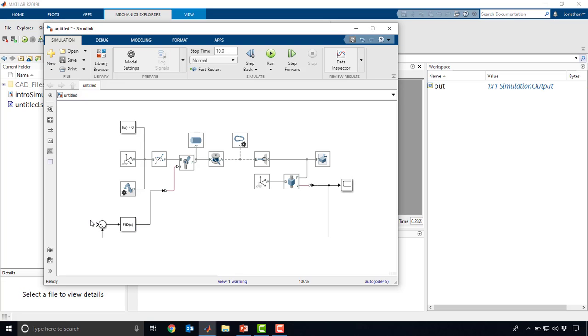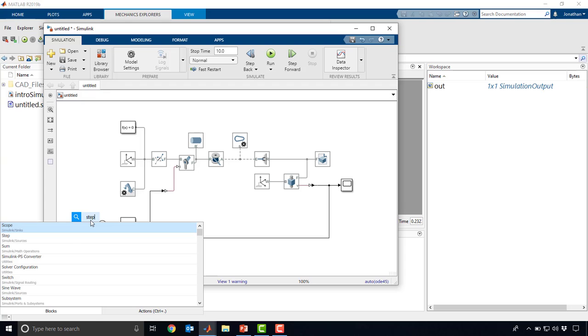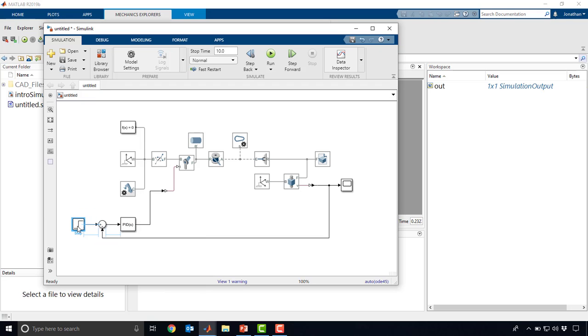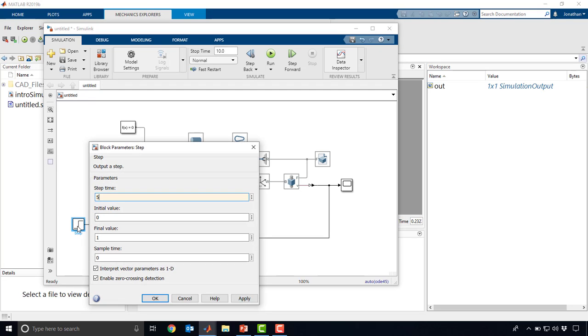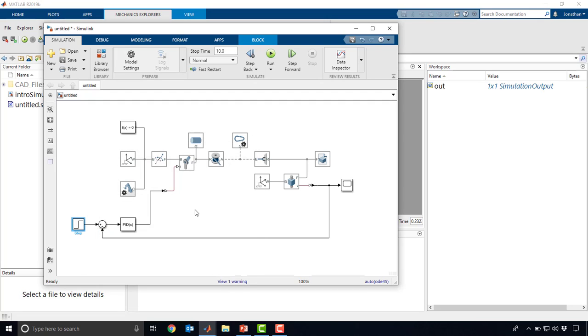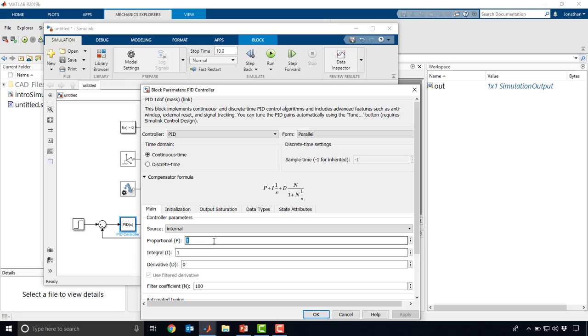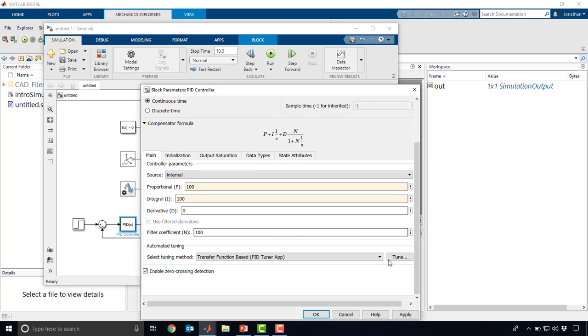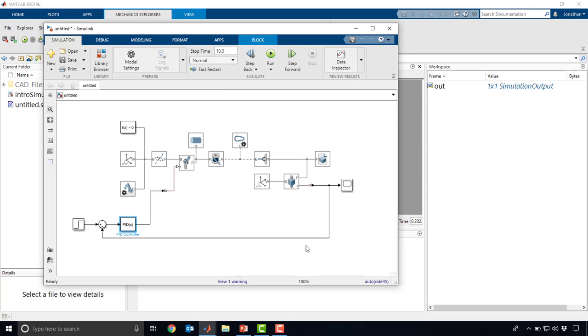That will go in there. And then we'll do like a step input. Okay. And maybe we'll make this step at 5 seconds, and we'll go down at 5 meters per second, and then we'll go up at 5 meters per second. And I know that this P and I are probably too low. I'm going to just manually jump these up a little bit, but I could actually jump in and start using our tuning tools directly already, and that would linearize our model and get us going real quick. But let's take a look.